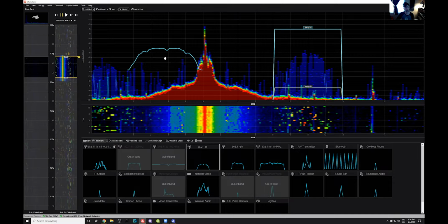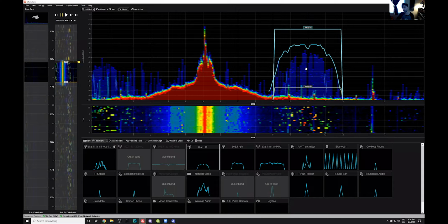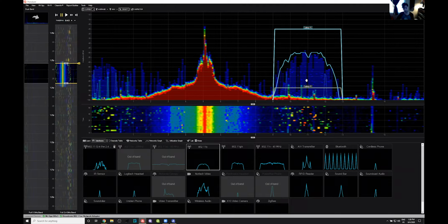And so right now I have some 802.11b signature here, and it's clearly not that, right? This is 20 megahertz wide. It fits more right here, right? And if you scroll, you can kind of manipulate the height of it, which is pretty neat. And so you can see that matches pretty well some 802.11b activity like I was talking about earlier with the DSSS modulation. Clearly not that.